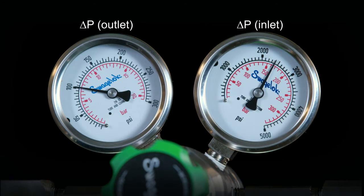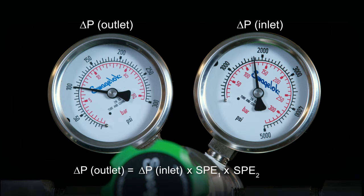The cylinder empties from 172 bar to 34 bar, or 2500 psig to 500 psig. Assume that each regulator has a 1% SPE. With a 137 bar or 2000 psig inlet pressure drop, the first-stage regulator will experience a 1.3 bar or 20 psig increase in outlet pressure.